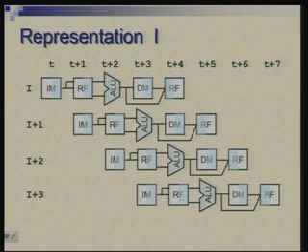So, here is the first approach. The horizontal line is the timeline, and each row would represent how an instruction is progressing. So, instruction I progresses through the 5 stages in time. Here time is in terms of clock cycles. I am not counting time in nanoseconds or microseconds, it is in terms of clock cycles. So, in cycle T it does instruction fetch, in cycle T plus 1 it does decode, and so on. It goes through the pipeline in the time cycles T to T plus 4. The next instruction enters the pipeline in time T plus 1 and leaves at T plus 5, and so on.